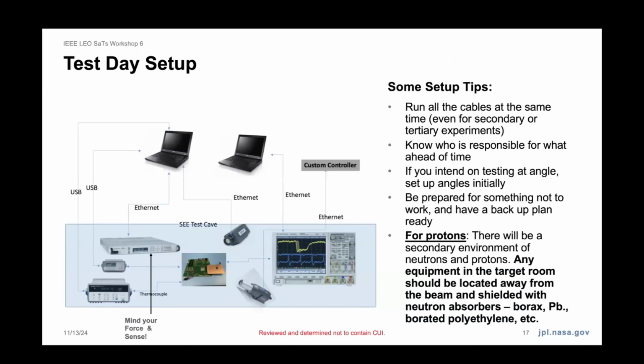A couple of other tips: run all the cables at once. Typically, there's a small pipe that you need to run things through. Once you start putting things in there, it gets difficult to run additional cables through. So even if it's a test that's 12 hours away, go ahead and run that cable now. Again, know who's responsible for what, roles and responsibilities.